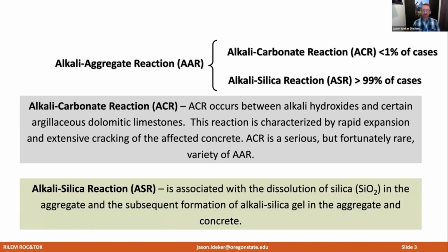Alkali silica reaction, on the other hand, is associated with the dissolution of silica in and from the aggregate and the subsequent formation of an alkali silica gel, or maybe a better term is an alkali silica reaction product that forms within the aggregate, and eventually as it cracks the concrete apart, that alkali reaction product will continue to work its way throughout the entire concrete matrix.